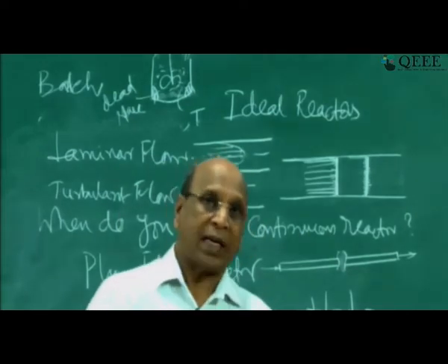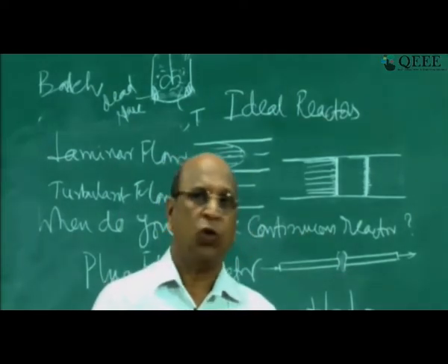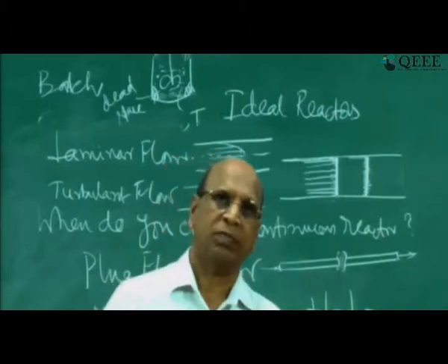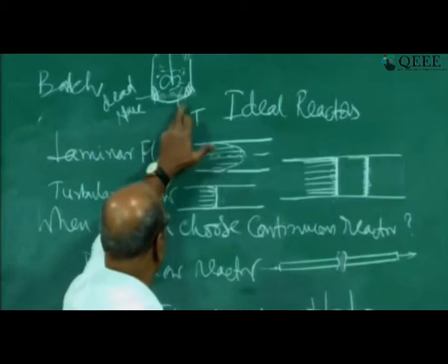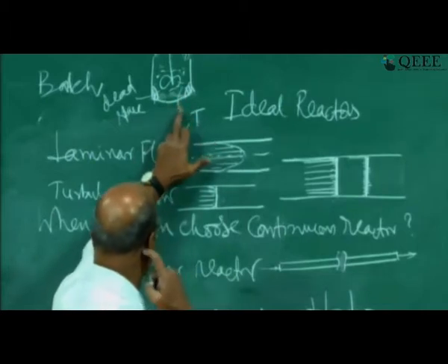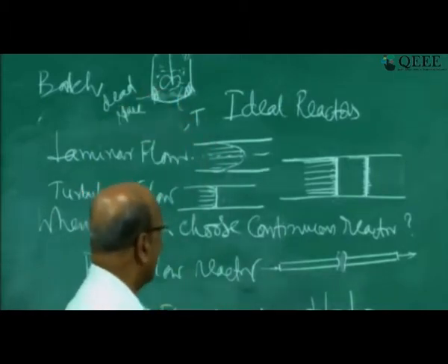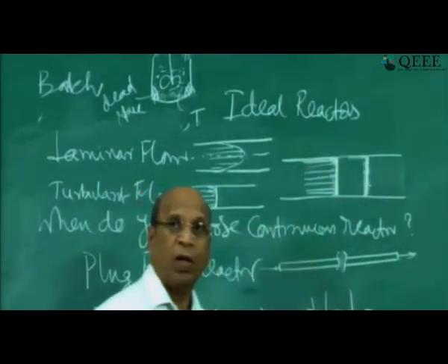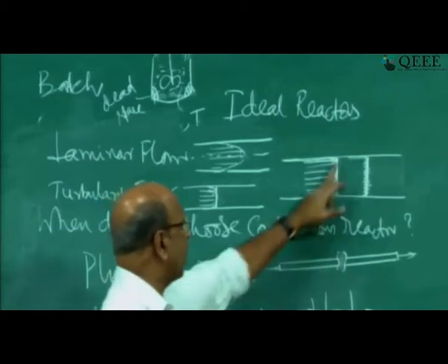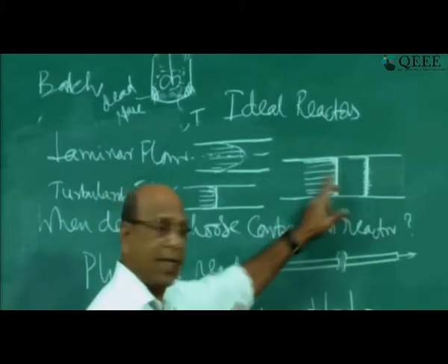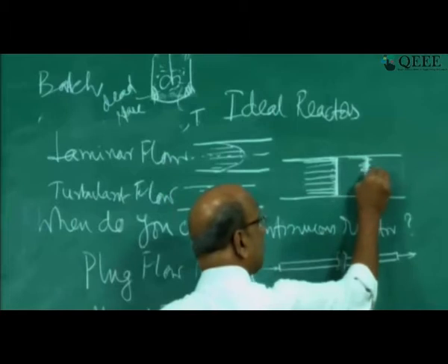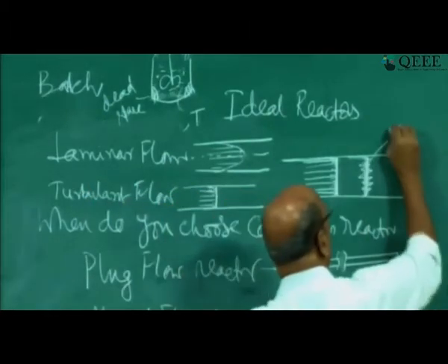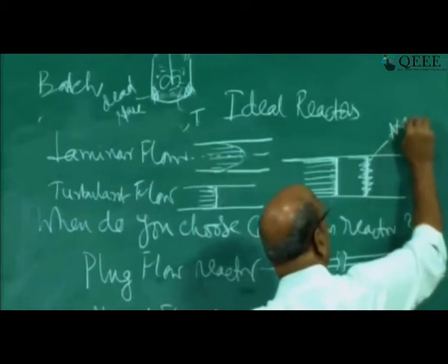For that kind of non-ideal batch reactor, you will not get the conversion you want in a given volume, right? That is the drawback, or the non-ideality, in the batch reactor. But what can be non-idealities in the plug flow? Plug flow requires a flat velocity profile like this, but in reality you may have what we call back mixing or axial mixing.